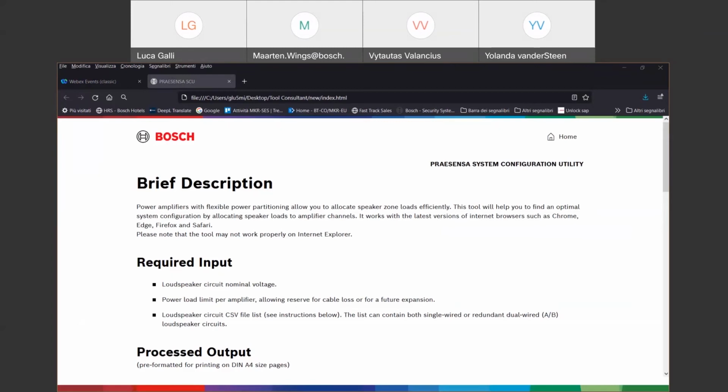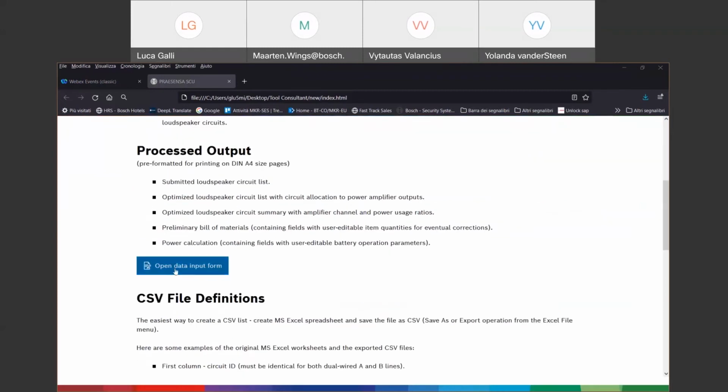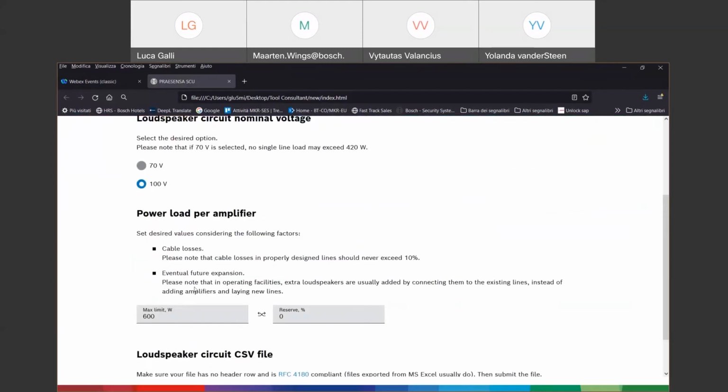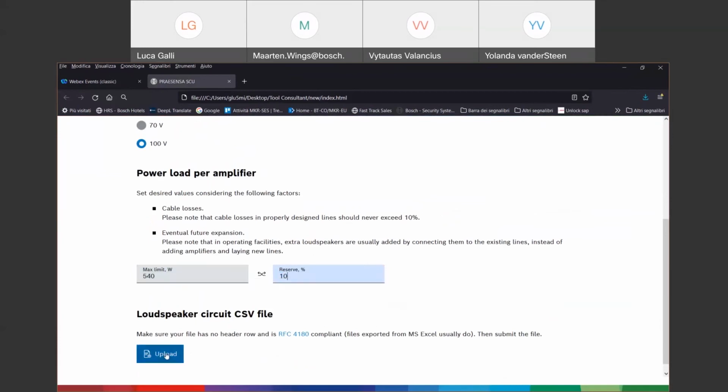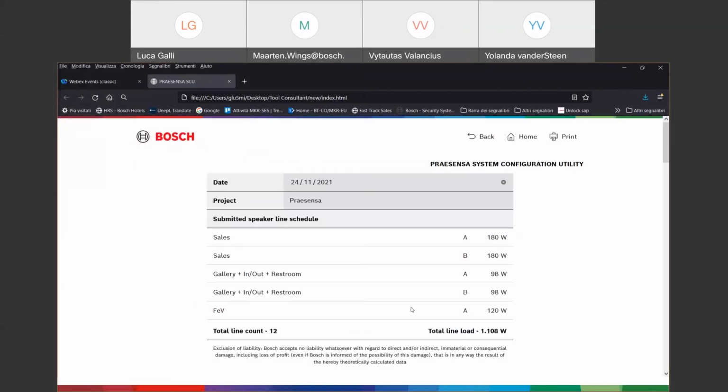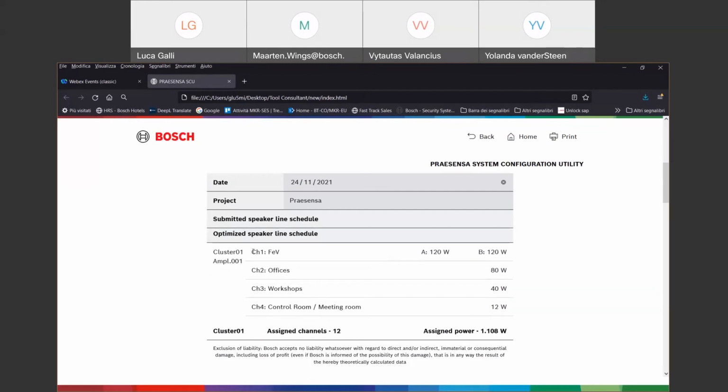I can comment on that as well. So actually, the design starts from the other way around. When you have a facility, first of all, you choose which speakers, which efficiency and how distributed you need to cover specific areas. And for that, you use the commonly available tools like Ease or the Ease Focus. There are several versions dedicated for that. Once you have your solution about how many loudspeakers of which type you have, then you can calculate the load per each speaker line, per each area, distribute them to physical speaker lines, and that information is what is needed for this tool. So before you use this tool, actually you should have it already. Yeah, that was shown on this slide with the consultant, right? It starts with the planning, and from the planning, exactly, you generate the input of the tool.